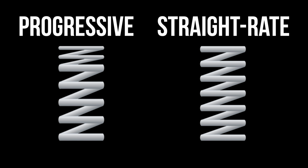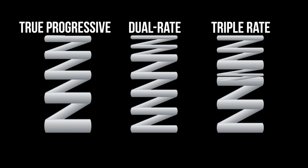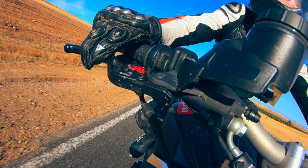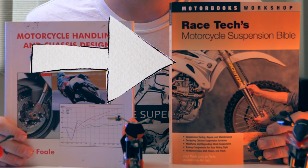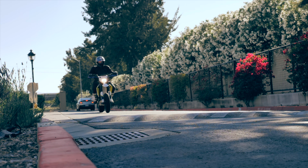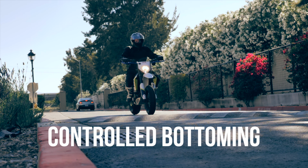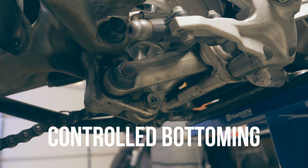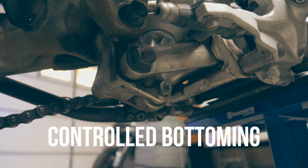Straight rate springs maintain a constant rate throughout its travel. Progressive springs change their rate in relation to where they are in their travel. There are many variations of progressive springs, with true progressive, dual rate, triple rate, and so forth. Which type of spring you need will depend on the application and personal preference. According to Racetech's Motorcycle Suspension Bible, straight rate will be the best option for most bikes and applications. Progressive springs have the advantage of providing controlled bottoming, which we talked about at the very beginning of the video. However, with a modern linkage rear end, bottoming out is not a big issue.